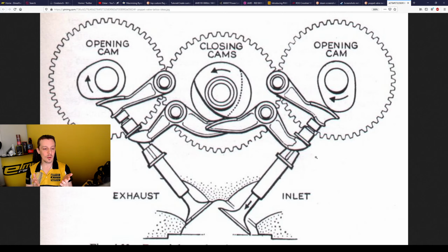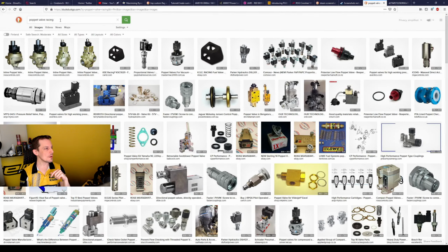as far as I know, state-of-the-art with Desmodromic systems is basically the flexibility of the closing cam and how that interacts. And then if you have a more complex opening cam solution with a finger follower, how the flex of this whole system works together. Because if you can figure that out and get it optimized, then you can run these to extremely high RPM. You could probably compete with pneumatic valve springs also. But okay, let's look at some traditional coil spring type systems.